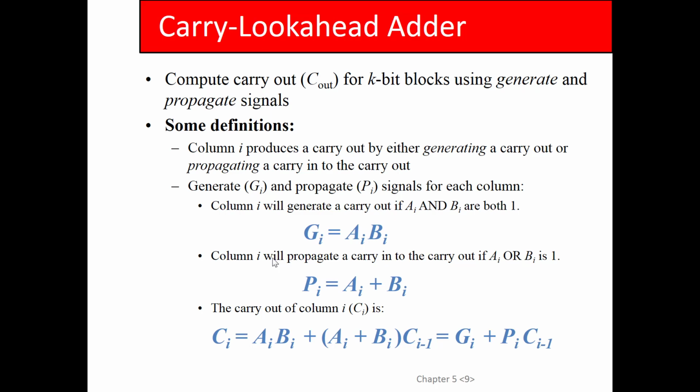It's not practical to do that because the adders get too big. There's too many input combinations to build a truth table for an adder, right? You've got 2 inputs of n bits. That means there's 2 raised to the 2n power rows in that truth table, right? So it's not practical to do it that way.